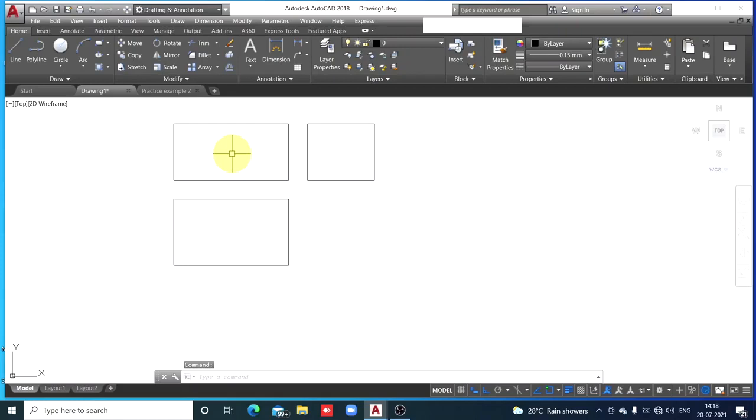So front and back are inseparable in the front view. You must know this, that this is the right side of the object, this is left side, top and bottom. In the top view, top and bottom are inseparable, but this is the right end, this is the left end, this is the front end and back end. So front end and back end, or front side and back side, are similar. So here you are going to draw a horizontal axis of symmetry, dividing this rectangle into two identical parts, front side and back side. So let's draw that axis of symmetry.